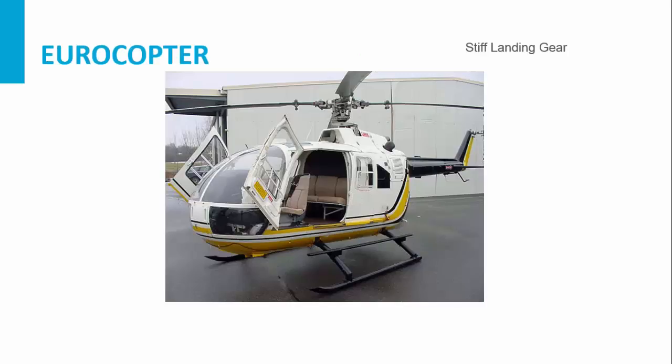The Eurocopter, you see that they used a stiff landing gear also to avoid the ground resonance. In this way, I ended the ground resonance phenomena. There are many instabilities in helicopters, and ground resonance is just an example of the problems that we have.